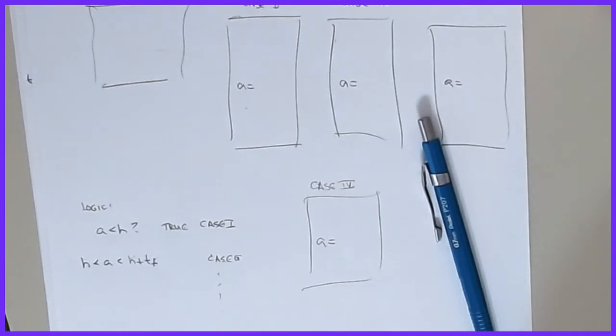Then all you do is, once it goes green, you know that now I can go do my moment capacity calculation, which is done the exact same way on all parts, and you're in business. You know exactly what the moment is when the slab works that way. Then you can go to the next step and start figuring out rebar size in the slab. But this is just the basic Whitney block calculator that I made. It's really, really handy.